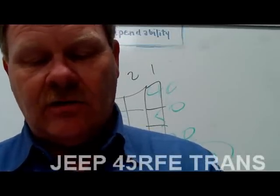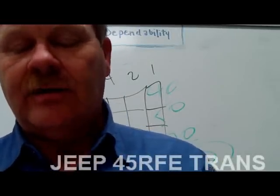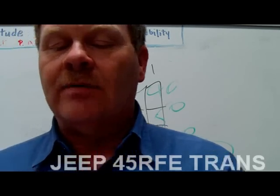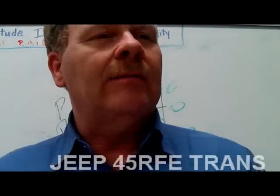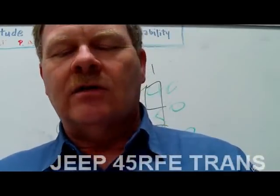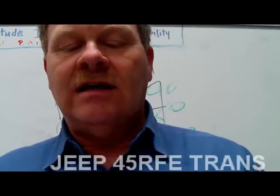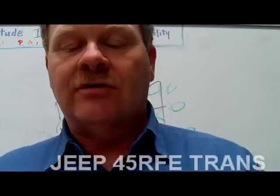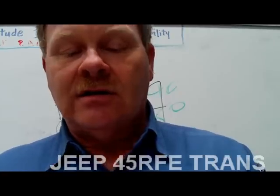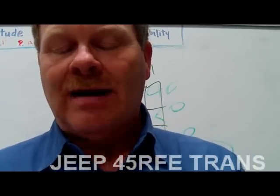All right, to control hydraulic pressure applied to the clutch packs, it turns the shift solenoids on or off depending on the desired gear. And the default position, now what's this? What's default mean? This is where it goes if it's not powered up. The default position of each shift solenoid varies. When it's de-energized, some solenoids are normally applied, and that allows fluid to pass through the clutch, and some solenoids are normally vented to route clutch fluid back to the sump.